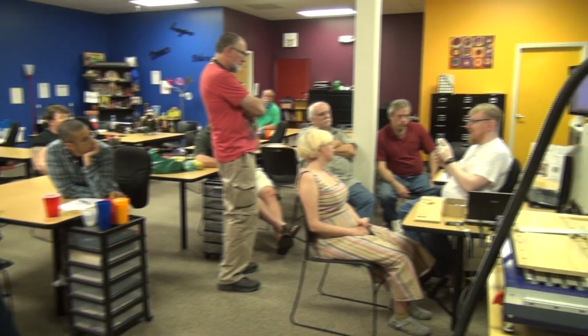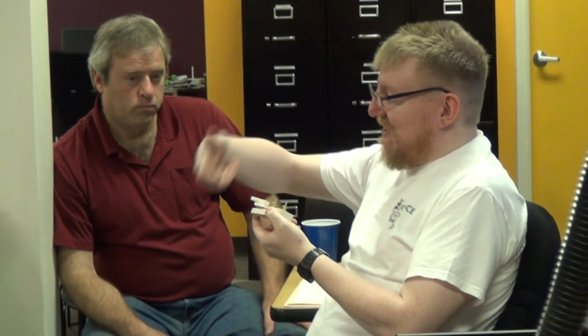This is a telegraph key assembled for my Reinventing Morse kit. This is cut out of the PVC lumber. The top button, you turn it upside down and sit it in front of it, and it machines it out of a 5-inch piece. There are several pocket passes that it makes. What I found, another interesting thing, is that the way I was doing it was cutting out this pocket, and then when you're done, you cut out the whole shape. Well, that was actually leaving a paper-thin wisp of plastic around the edge.